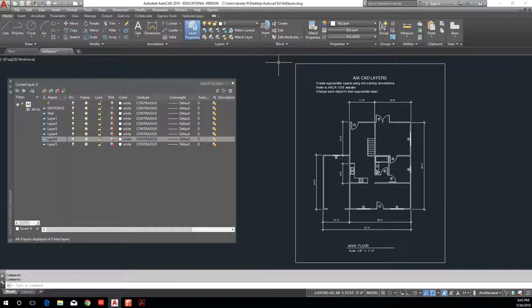They come to me panicked: I've got my assignment done, but I can't print it, nothing is showing up, it's on model space. The number one thing I ask is, is it on a printable layer? The answer is always, yeah, it is. Then I look at their drawing and no, it's not. This is probably one of the biggest mistakes beginning students make.